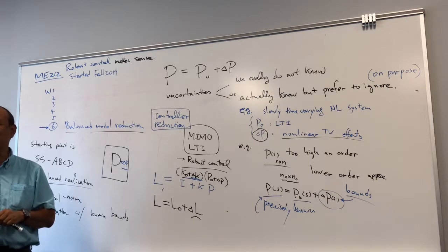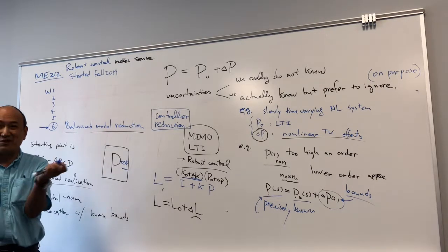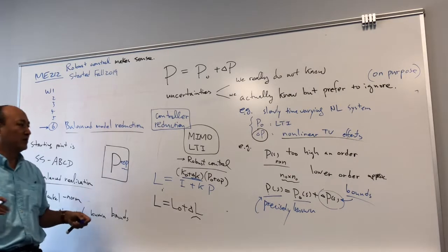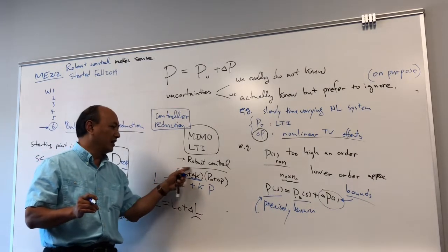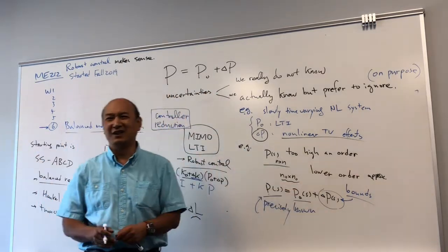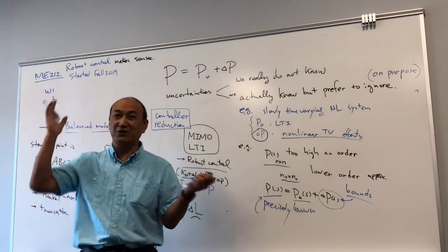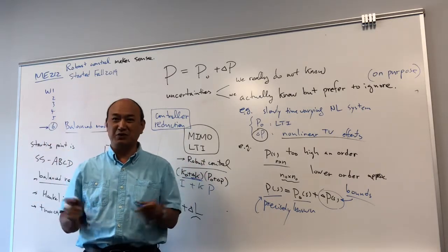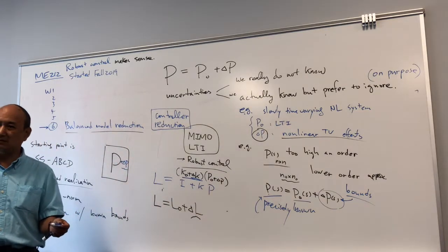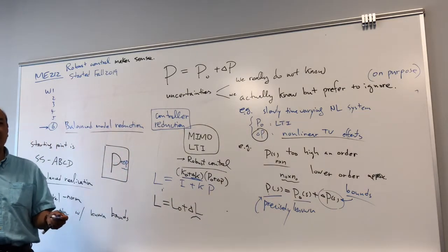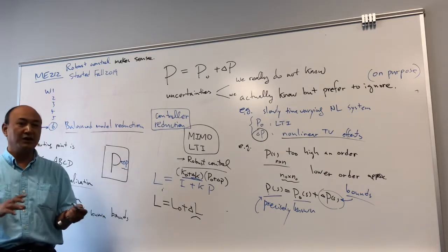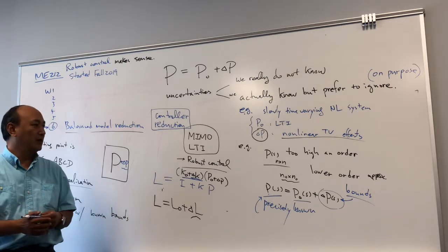Usually when you get a controller, you just implement it, right? But in robust control, the controller is often also too high an order, very big, like order 40, a 40th-degree polynomial. Then you have issues with numeric accuracy, accumulation, and internal state divergence in your realization.